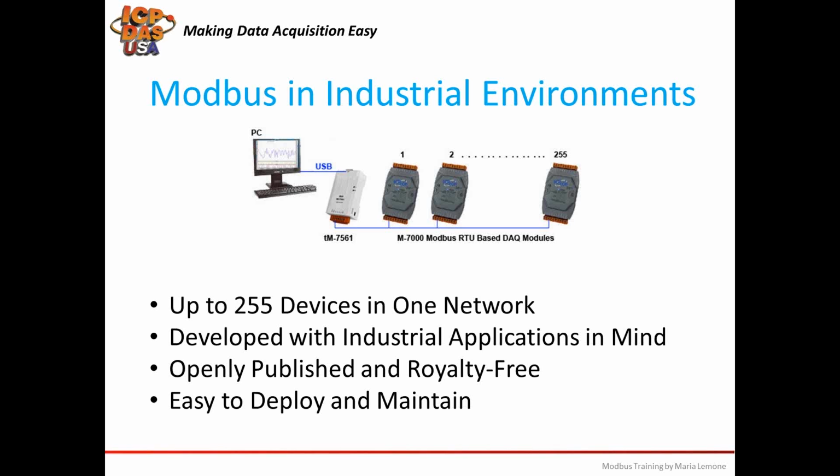Right. I considered, I'm sorry, that the customer might have an existing system which already supports Modbus RTU. So if the customer has this kind of application, we can also use Modbus RTU devices with our Modbus TCP devices and carry them through Ethernet communication. Right.